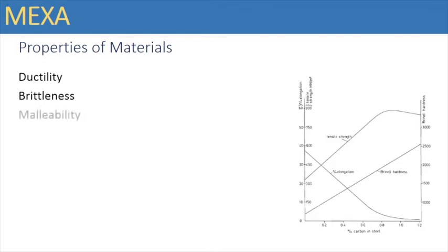Malleability. It is a property similar to ductility. If a material can be easily beaten or rolled into plate form, it is said to be malleable. Elasticity. If all the strain in a stressed material disappears upon removal of the stress, the material is said to be elastic. Plasticity. If none of the strain in a stressed material disappears upon removal of the stress, the material is considered plastic. Hardness. A material's resistance to erosion or wear indicates the hardness of the material.